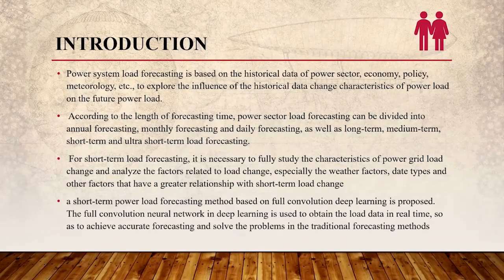Power system load forecasting is based on the historical data of power sector, economy, policy, meteorology, etc., to explore the influence of the historical data, change characteristics of power load on the future power load, and define the possible relationship between power load and various related factors, so as to correctly predict the future power load. According to the length of forecasting time, power sector load forecasting can be divided into annual forecasting, monthly forecasting and daily forecasting, as well as long-term, medium-term, short-term and ultra-short-term load forecasting.